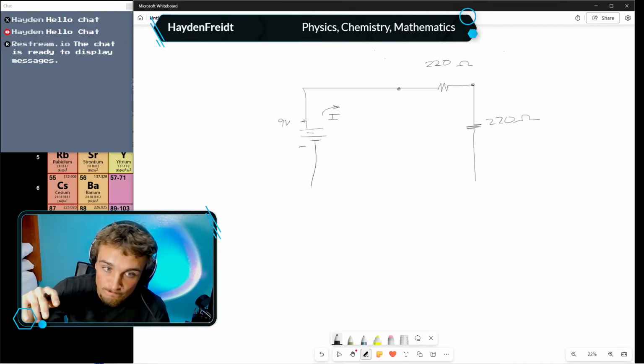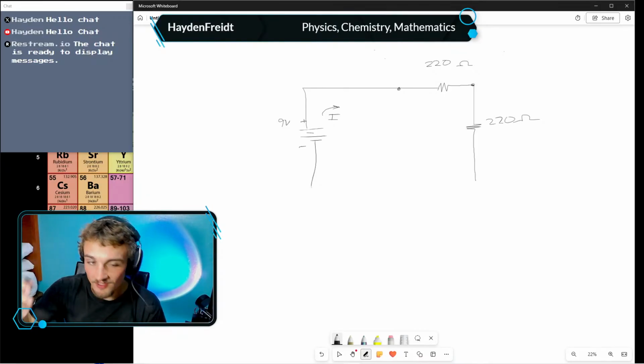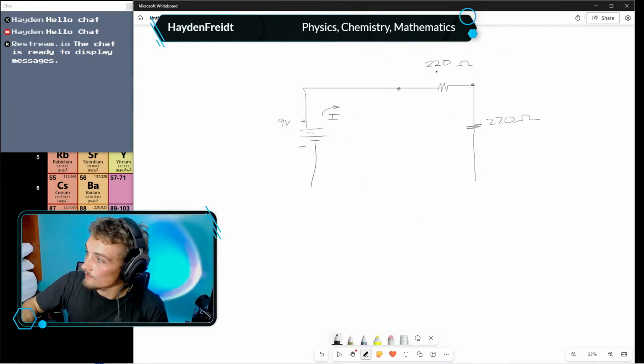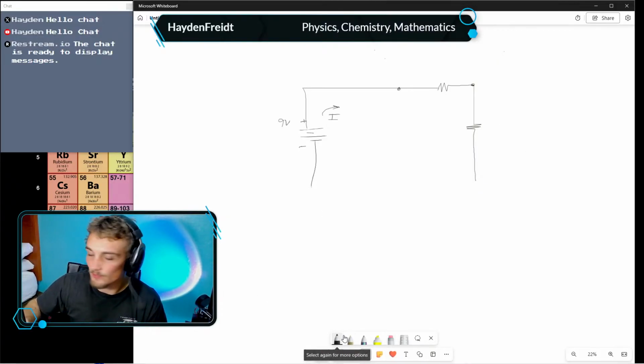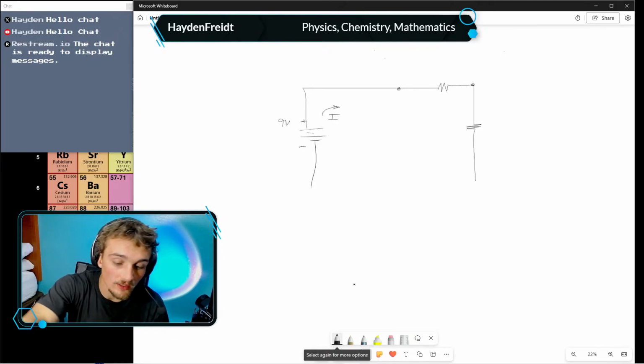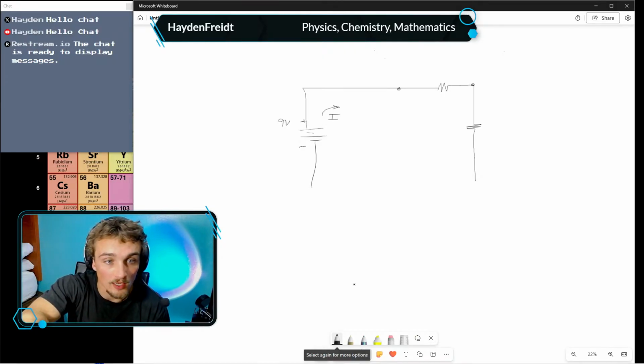Because what I'm really going to do is I need 4 volts across one of the resistors, and I need 5 volts across the other to supply the LEDs. I don't really want any less than 5 volts. So this is the point at which we're at now. I'm just going to draw everything out first before we start giving values. I'm just gonna write down the values that I currently have because I know this circuit operates correctly, and I guess perhaps I can show you on camera how it operates.